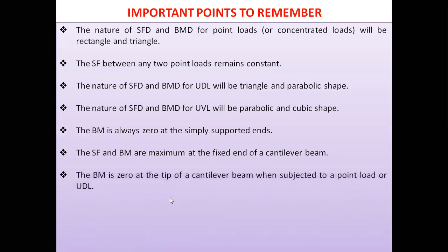The bending moment is zero at the tip of a cantilever beam when subjected to a point load or uniformly distributed load. The shear force is zero at the tip of a cantilever beam when subjected to a UDL.